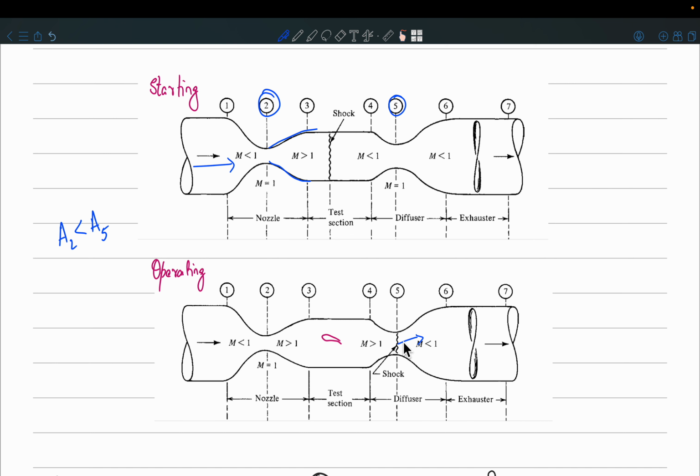That subsonic flow doesn't matter, no? What matters is the pressure ratio and the strength of the shock. So the further you decrease this pressure, you are basically increasing the inlet supersonic flow Mach number. And that is what determines the shock strength.